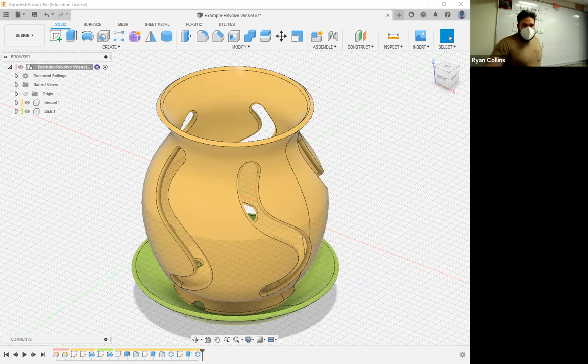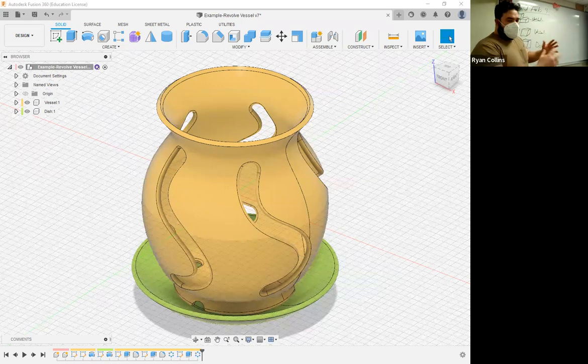That's okay. It's good. Yes, go ahead and do some auto selecting for me, please, and thank you. And let's just say, let's go to draft. Yep, that's fine. Transfer over. Build plate only, 20% is a bit excessive. PET is my material, and my printer is selected properly. Now, if I go to slice, what's going to happen is it's going to automatically generate supports, scaffolding, because a dish like that is far too low for it to print without.